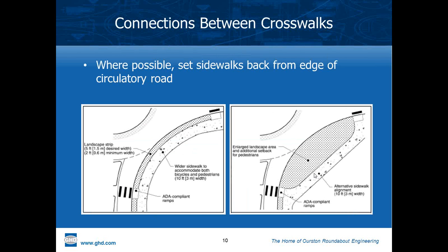In the roundabout guide, the Federal Highway Administration's NCHRP 672, these diagrams are provided just to show the desirability of additional separation from the back of sidewalk. The U.S. Access Board requires a strip of contrasting treatment, either tactile or visual, to separate the sidewalk from the traveled way, and not just the back of curb and grass. It should be something tactile, so that the visually impaired pedestrian doesn't venture out into areas and cross where it's unsafe to do so.